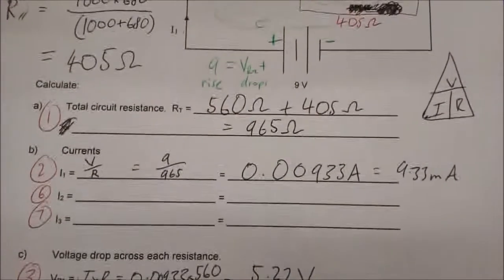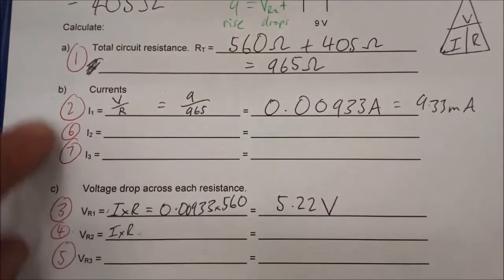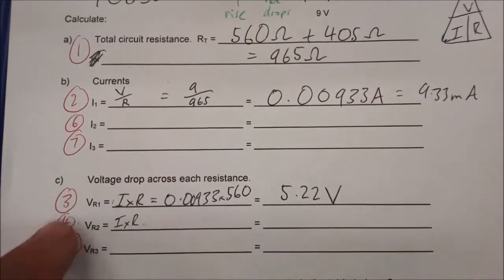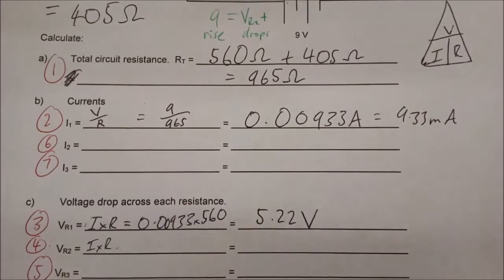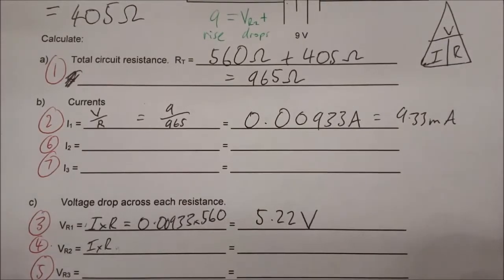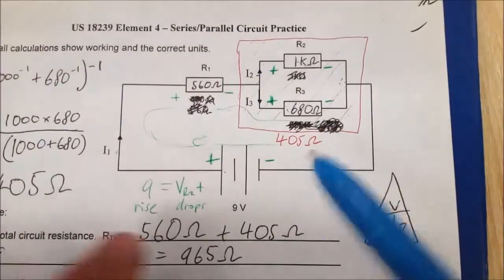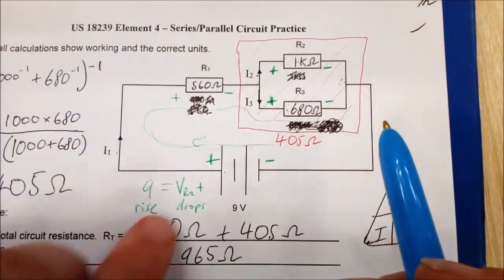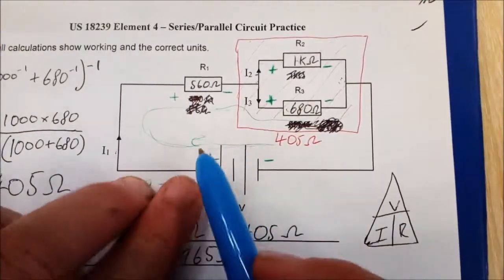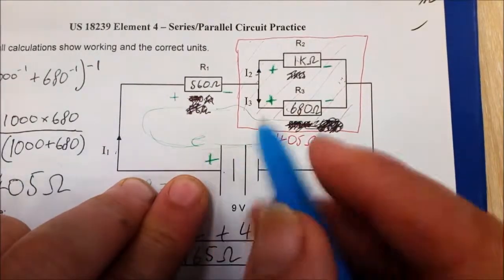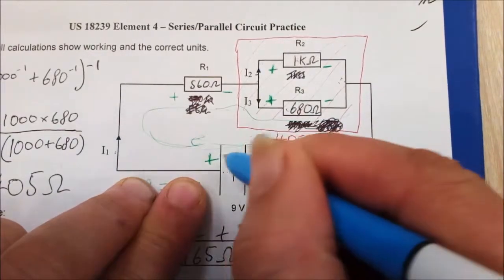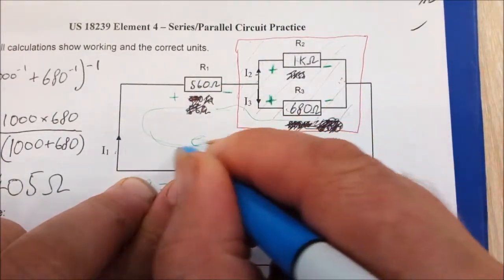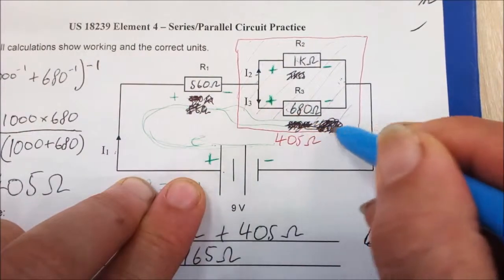And there are a few of them, but I'm going to, as you see, I've numbered this. I'm going to tackle this one here, the voltage, before going back to the current, just because I think that's probably the best approach to take. So we have to consider, and I've already started writing here, the voltages around the circuit. If we go around, we'll just choose one path to get from the positive back to the negative again. We'll take the inner path around here.